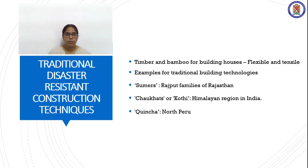The doors and windows should be very few, small and symmetrically placed away from the corners. The houses should be as light as possible. It should not be heavier structures. The earthquake resistant structures adopted by Rajput families of Rajasthan in India is called summers, and chaukats or khoti is the traditional building technology adopted in Himalayan regions.